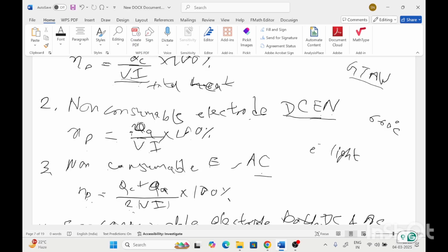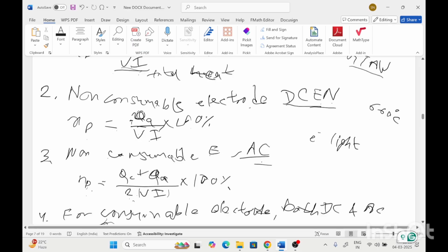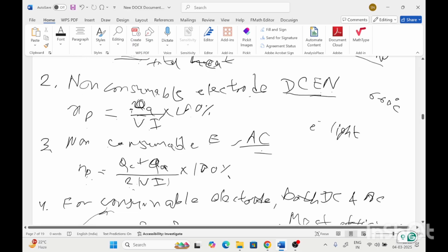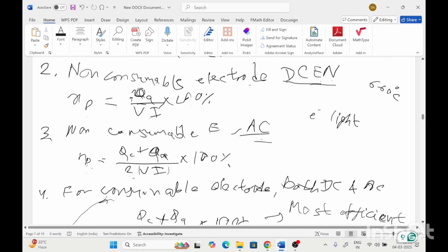As the electrons move from the electrode to the workpiece, they strike the workpiece, increase its temperature, and lead to melting. So for aluminium, we use AC current. Okay, ma'am. So in the first cycle the workpiece gets cleaned, and in the second cycle the welding is done.